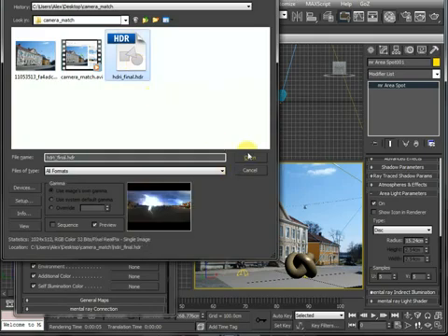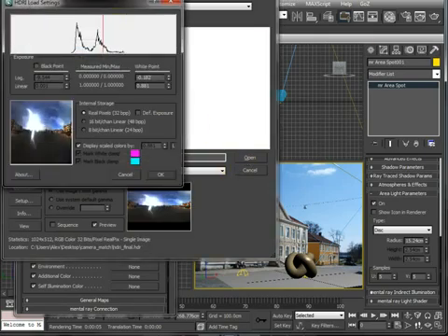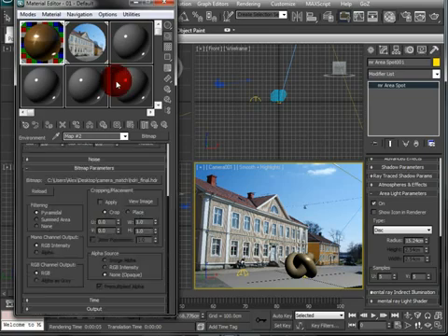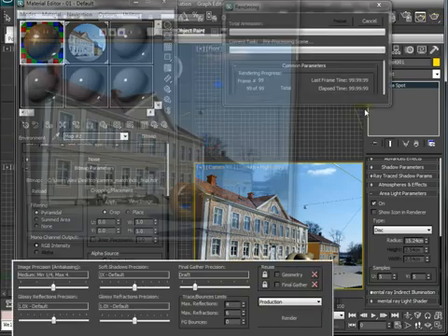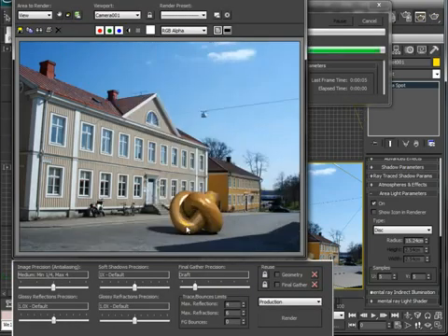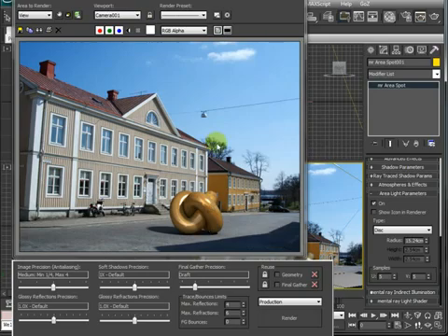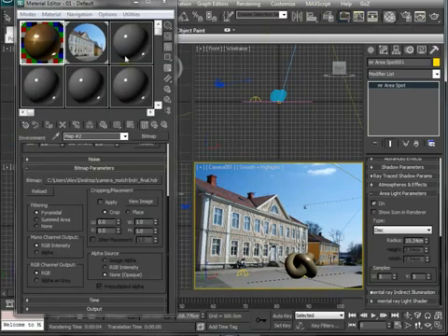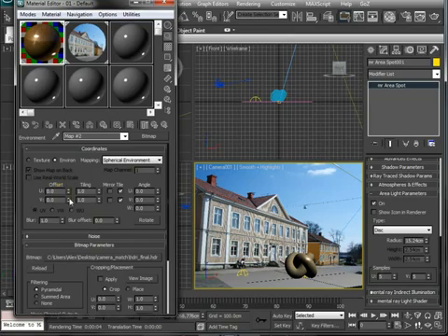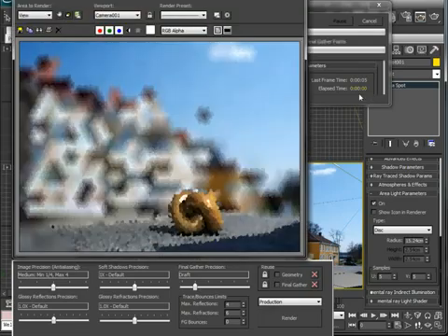There is a tutorial I've made specifically on how to work with these files within 3D Studio Max, so I recommend having a look at that and seeing what the tricks are with that. But if we have a quick look, excellent, you can see that now we've got a bit of reflection in there as well, this hot spot from the light. If you want to move how that image texture is set out, in the texture tab you can start playing with the offset of that texture and do another quick render to see how that's moved the light spots for us, which will do nicely.